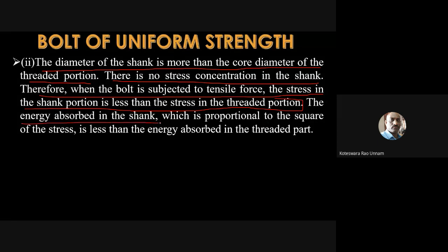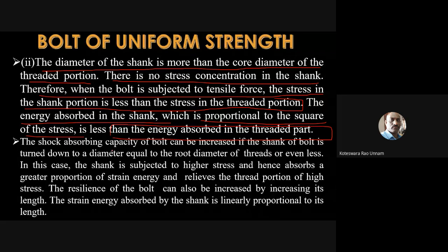Then the energy absorbed in the shank, which is proportional to the square of the stress, again is less than the energy absorbed by the threaded portion. That's what I already told you. So the less energy absorbed means the capability of absorbing shocks is very less. The shock absorbing capacity of the bolt can be increased.